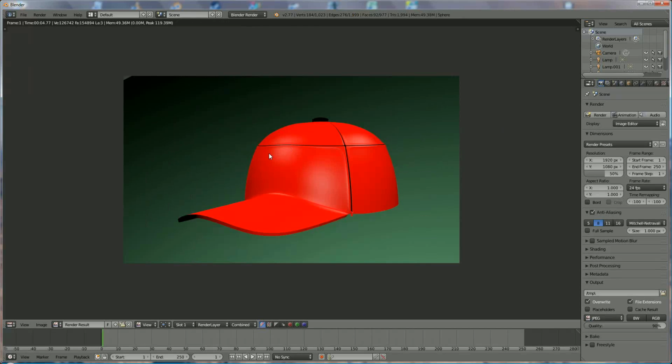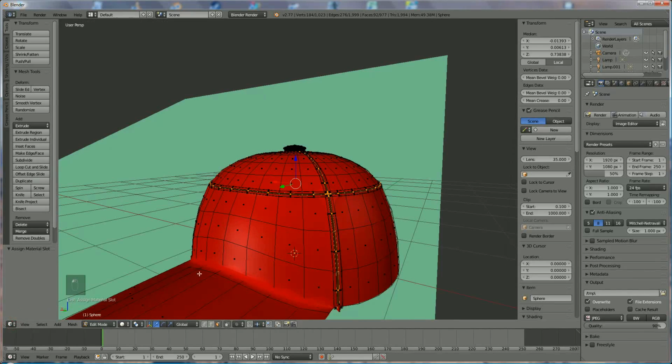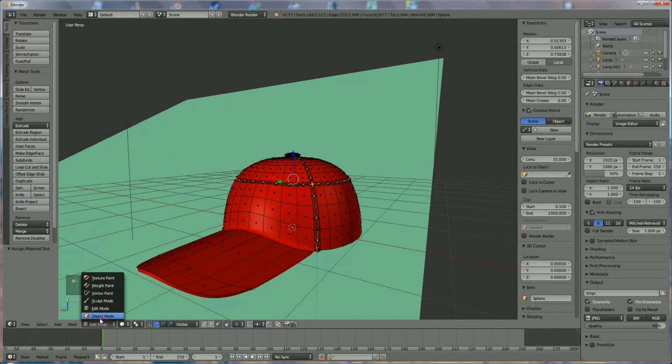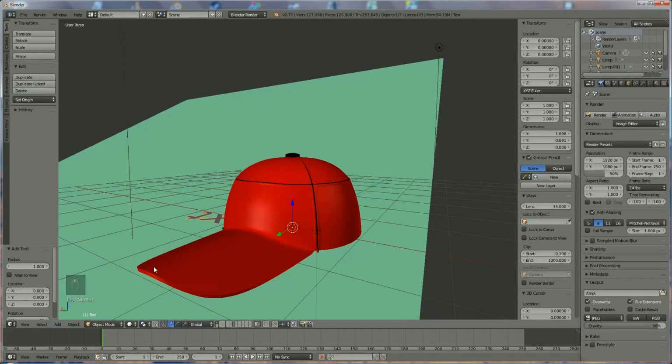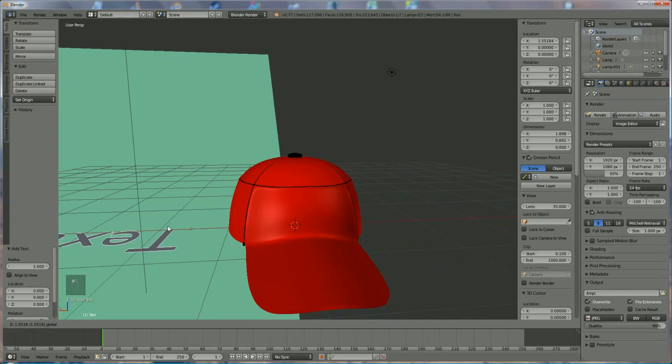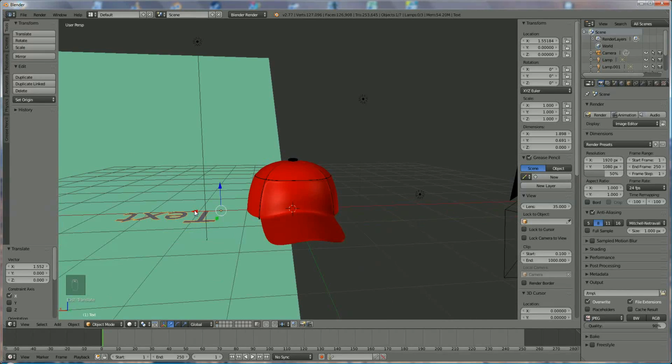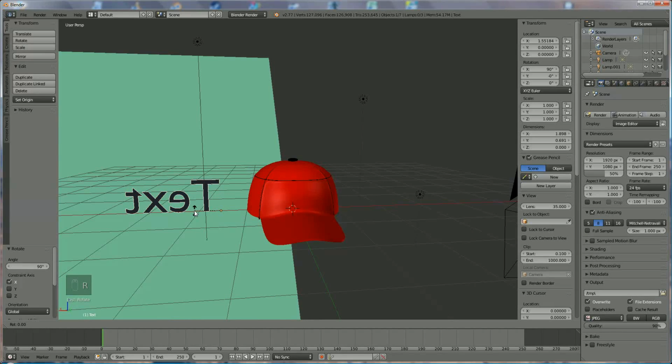Okay, now I want my name over here, so go back to 3D, switch to object mode, where we're going to add a text. Okay, so I'm going to bring it outside so that you see what you have. We have to rotate it in X direction 90 degrees, like that. Click on enter, and we're going to rotate it in Z direction 180 degrees. So RZ 180.